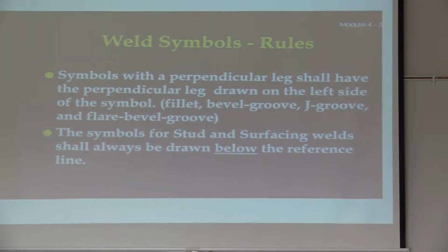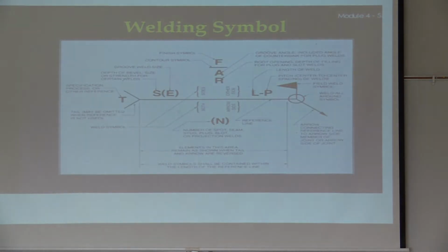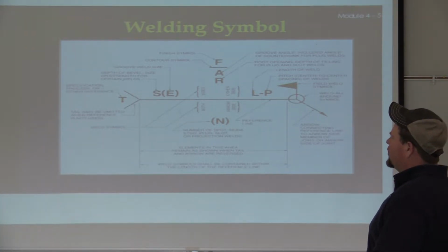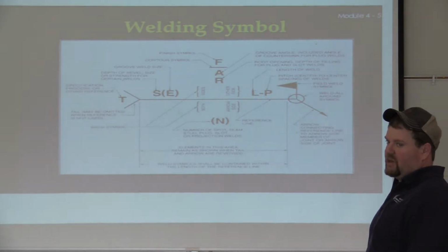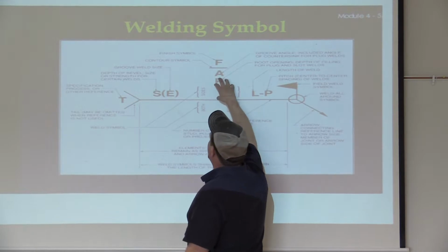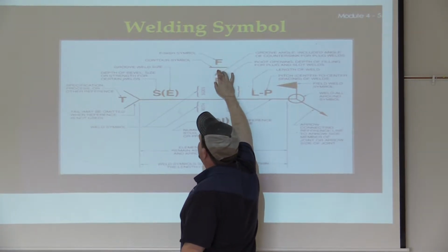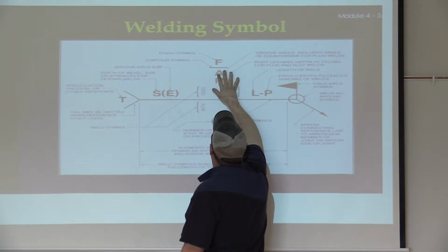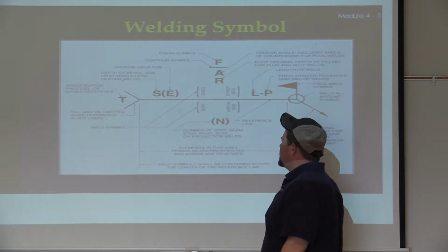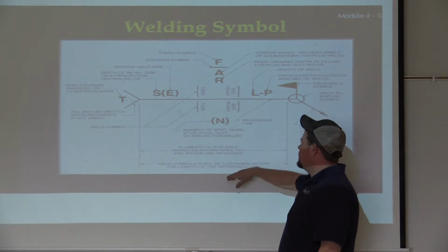In that direction. Okay. This is the symbol we've got in the shop. Take a picture of it. You write it down, and this is your recipe. You can figure almost anything out from this portion alone, just process of elimination. Okay? Again, actually our weld, arrow side, other side, finishing contour, the actual groove angle, and then the root opening in this section, number of spot seam welds, elements in this area being shown.